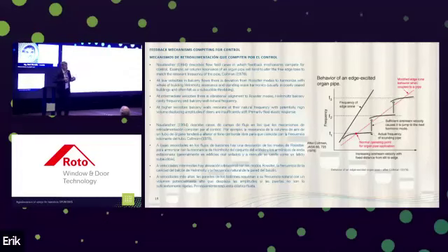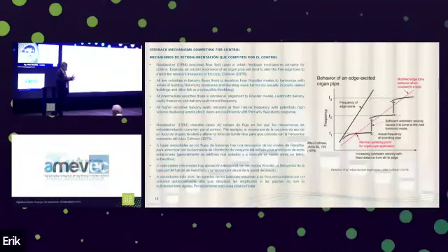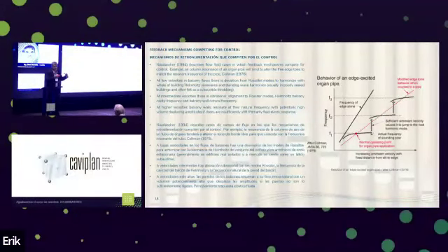Now, the same thing can happen in real building flows. At low velocities, say, for example, in a balcony cavity, there is a deviation from Rossiter modes to harmonize with whole building Helmholtz resonance and standing wave modes. Now, this usually occurs in poorly sealed buildings where the whole building volume is exposed and can resonate with low frequency Rossiter excitations. As the wind velocity increases, keeping in mind these are glancing wind directions, so does the Rossiter excitation, so it's going to harmonize with smaller building volumes, for example, a balcony cavity.